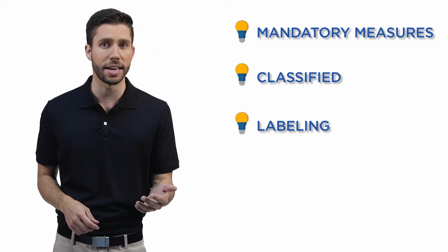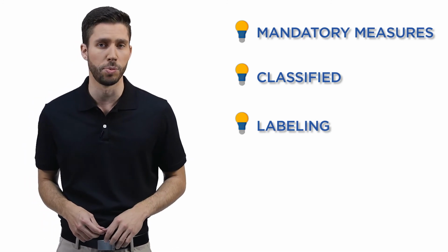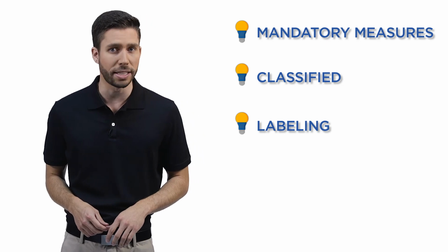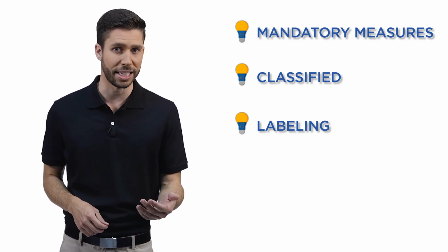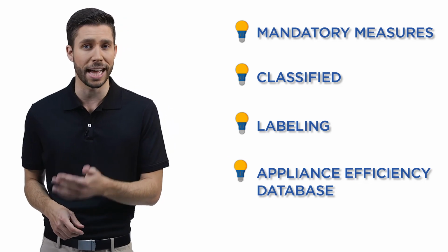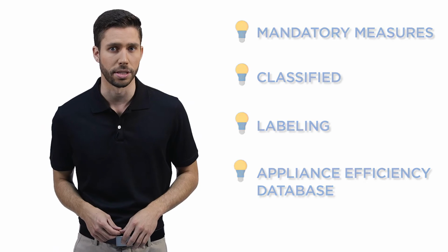Only JA8-2016-E sources can be used in enclosed luminaires and recessed ceiling downlights. No screw-base sockets can be used in recessed ceiling downlights. And we have discussed the Appliance Efficiency Database as it is related to high efficacy light sources.